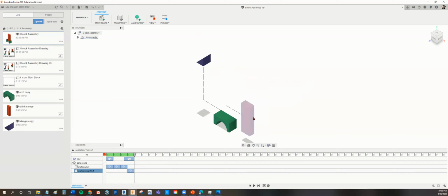Right. This time I want one more transformation. I want this one to go up. Okay. So I'm going to click transform, drop down to manual explode. But click on the up arrow because I want this one to go up. Here's the transformation window. Make sure the trail line is on. All right, I'm going to toggle, see how it goes far up. Let's see, I'm going to go that far, then hit OK.